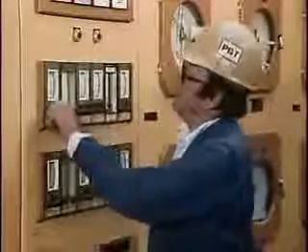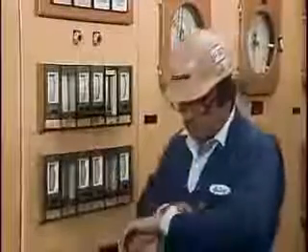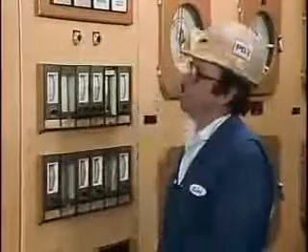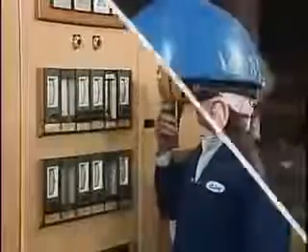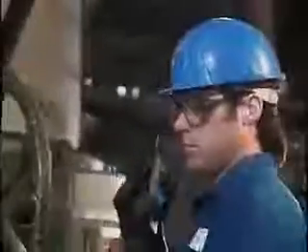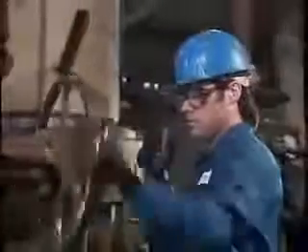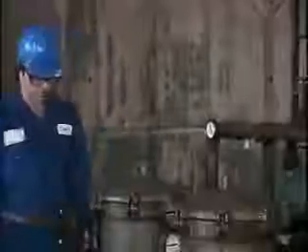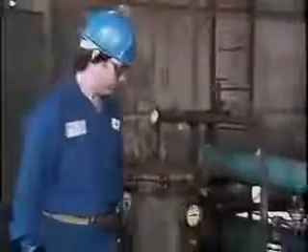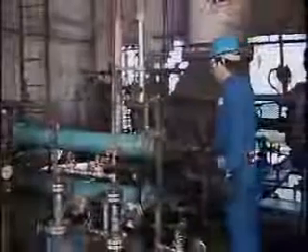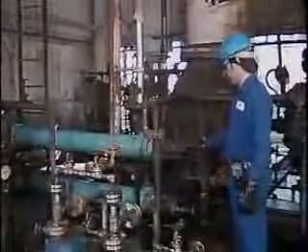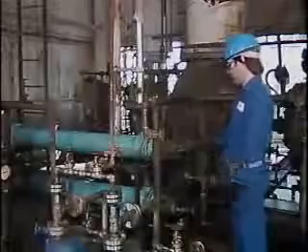Once the compressor has been purged, it is started and allowed to warm up. The steam turbine is started at a low speed to allow the compressor to warm up. The steam turbine is started by opening the steam supply valve. As the compressor is warming up, it's important to make sure that the proper flow of cooling water is maintained to the lube oil cooler. The compressor could be damaged if the lube oil temperature is allowed to get too high.